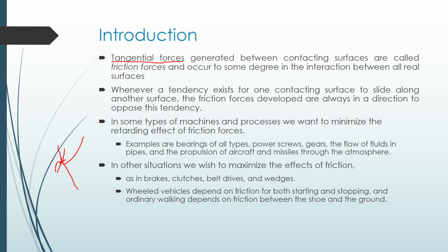As a result, over a period of time, the inner core or wire, the cable surface, tends to loosen up. Although you apply the clutch so often, the fatigue life of steel is very high. As a result, the amount of force you apply is not significant enough to break the cable, but it is that friction that causes a gradual erosion of the cable. As a result, it snaps.